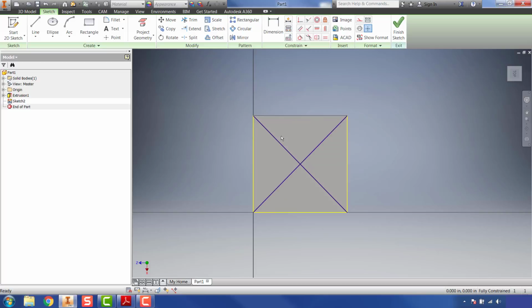So I'm going to use the other selection box, which is pulling from bottom right to top left, and gives me a green selection box. I want to select those two lines, and I'm going to turn those into construction lines, and then click off and make sure that that construction line is not selected, and it's not. Now I'm going to grab my ellipse tool, use that center point, and I want to make sure I make a totally horizontal axis here, and you'll notice that constraint pops up when it's horizontal. And just approximate where this goes and go ahead and left click to place it.